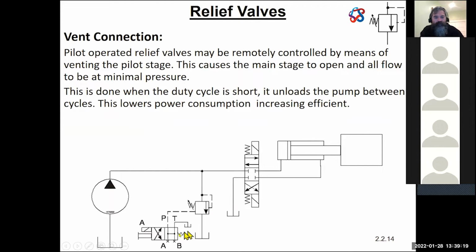So in normal operations, remember the spring on the valve here, the 2-4 valve at the bottom, 2 positions, 4 ports. Even though 2 ports are blocked, we still refer to those as 4 ports. It's holding it in this current position here. So what will happen? Well, if I run the motor, fluid wants to build up pressure, but if I track back through this valve from tank,